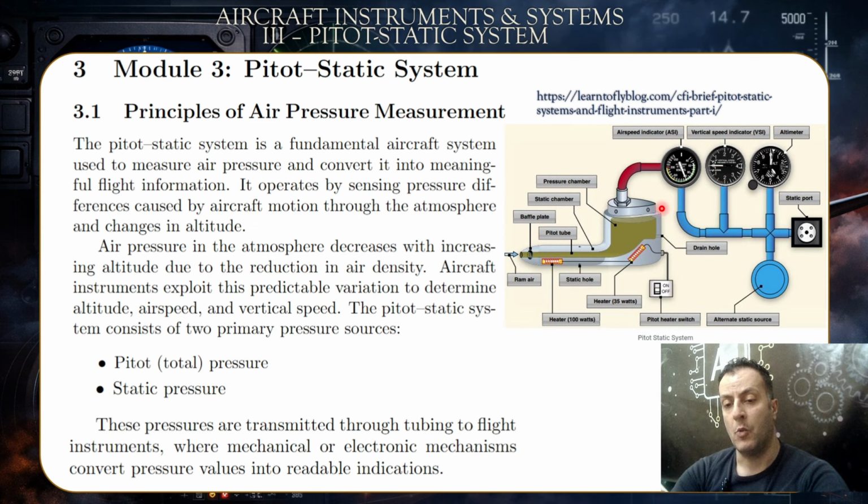You see, when you have a blockage, icing in this case, any type of blockage is bad. And this is why, by the way, you have the heater, in order to melt the ice to prevent any blockage of the pitot tube. But when you have icing during takeoff, the airspeed would appear to be very slow. Why? Because the density of the air at ground level would prevent the air from flowing in an efficient way within the tube, depending on the rate of the blockage.